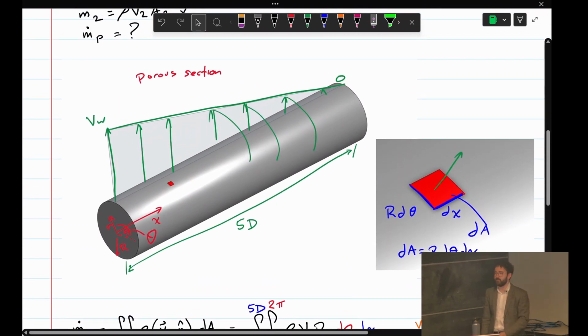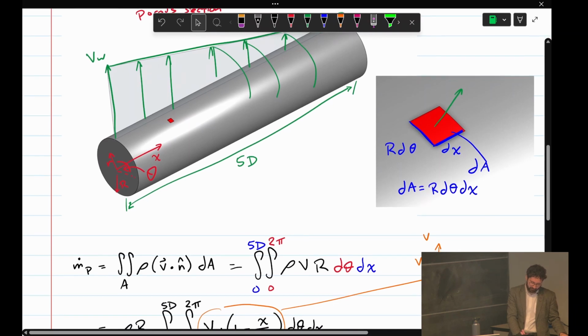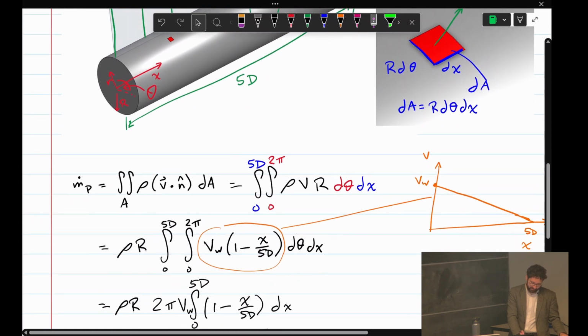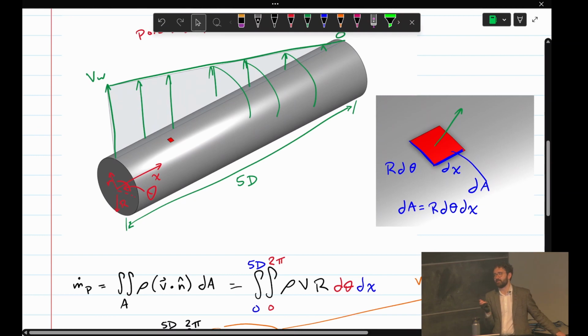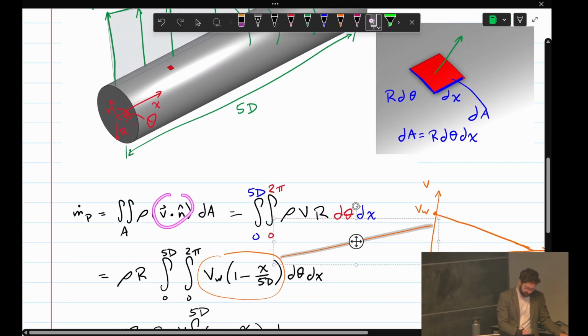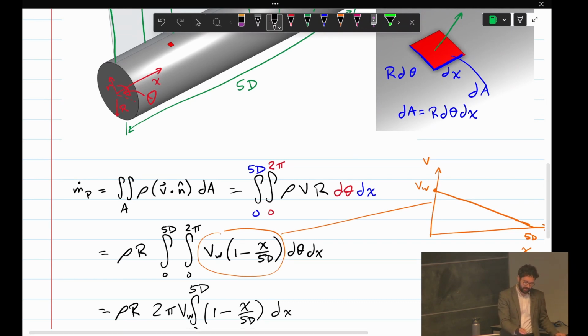Yeah, you could definitely have tangential velocity. In this question, we've assumed straight normal velocity. So in that case, you need to account for that in the mass balance as well. Let me think about how you do that. I think you would just do the same integration, but in your mass balance in that direction, you wouldn't have all of the velocity turn into v dot n. Some of the velocity would turn into a tangential component. But that's why this question is nice, because it's all straight normal.